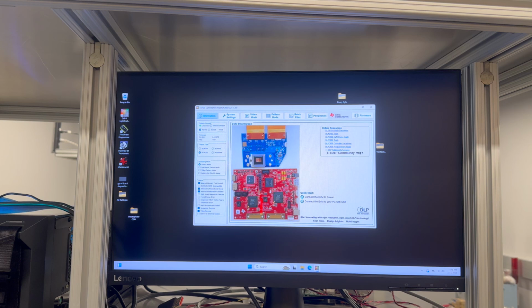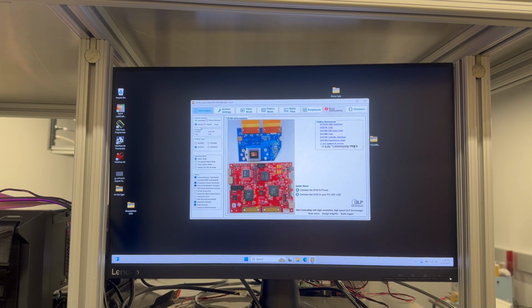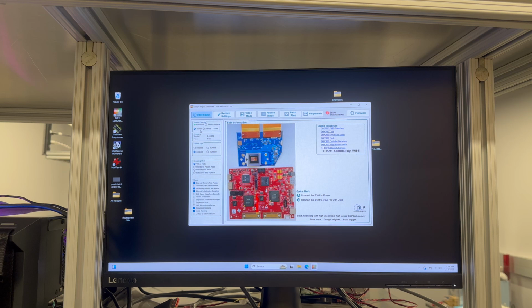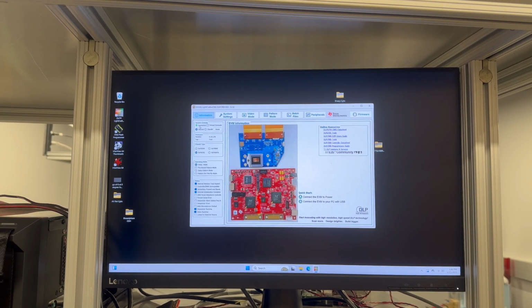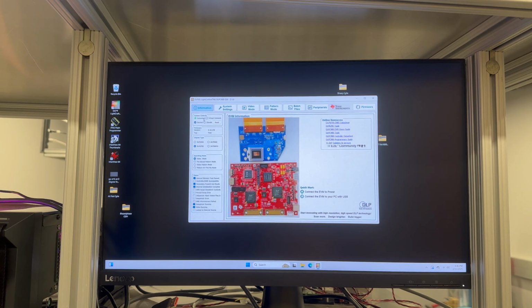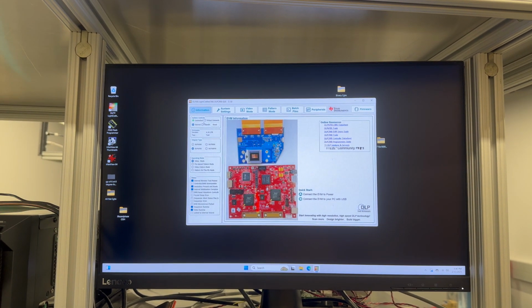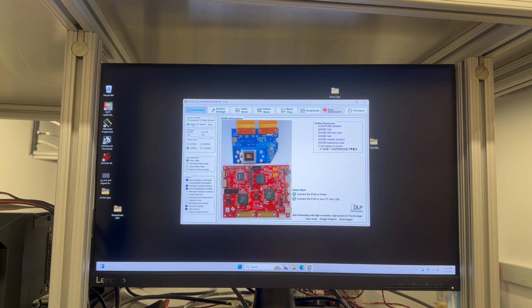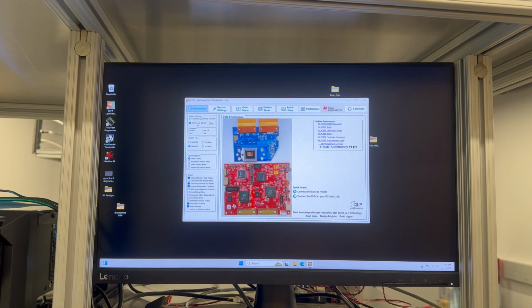Right now, we will turn on the GUI, and here it will show connected, and it's normal. Before, in the slide, I had to talk about this. When it shows disconnected, we will change the controller board, and when it shows standby, we have to change the daughter card. Right now it's normal, that means it's a good connection.